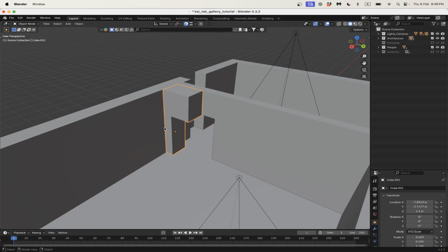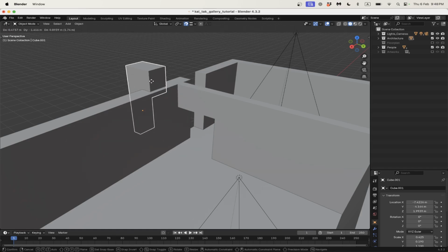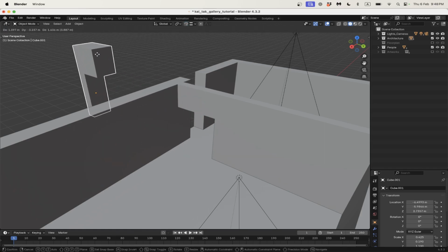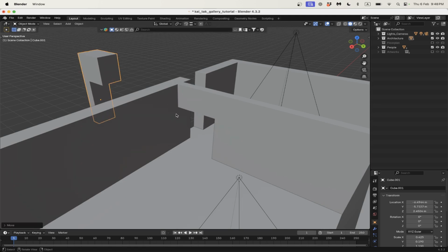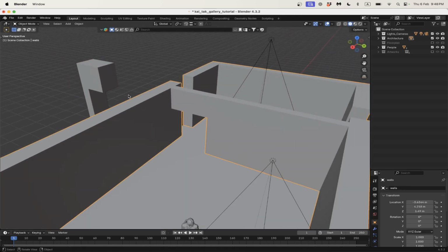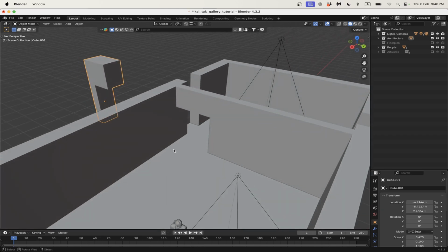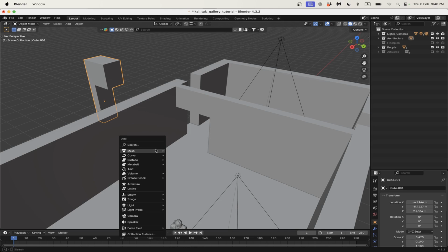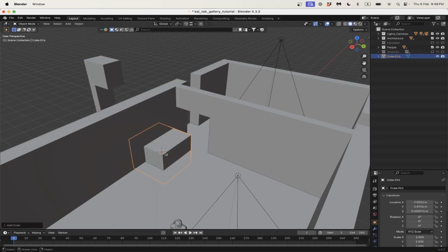What I'm going to do is make this object as a little measuring device, and then we're going to use that to build it into our actual wall object here. So we'll make this again. I'm going to make a new cube. I'm going to press Shift right click, and that places this thing here. It's called the 3D cursor, and it's got lots of uses, but in this case, when I Shift right click here and then add an object by pressing Shift A, Mesh and Cube, it'll add the cube where the 3D cursor is. It's just convenient, so it doesn't add it somewhere off my screen.